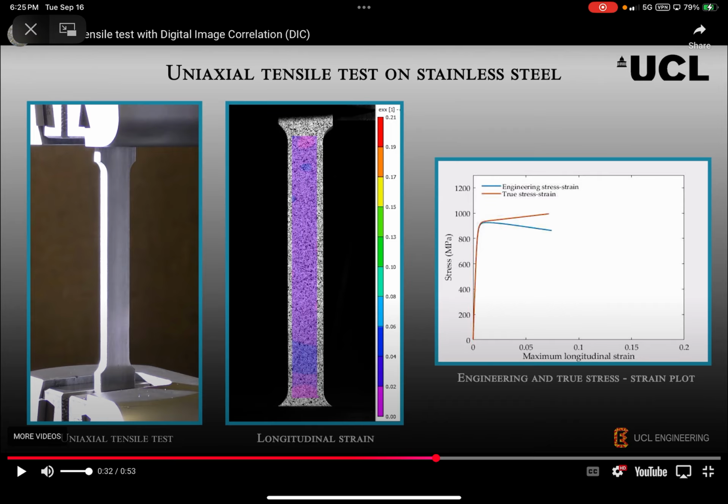So what you guys notice is the true stress versus engineering stress strain. The engineering stress strain, I'm presuming, is... No, never mind. Ignore what I said. So the engineering stress is what we design with. This assumes that the cross-sectional area remains constant as we're designing material. But what's happening as you stretch it? Like, what's happening to the cross-section? The cross-section is slightly changing, right? You could think of it like if you're pulling on something, the size of the cross-section is just going to be getting smaller. And I'll draw that out just like this.